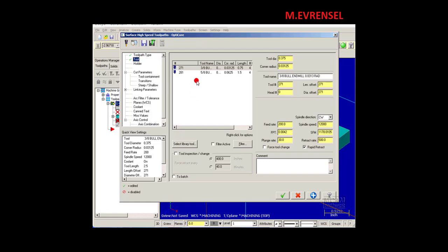The general strategy for using them is use a smaller diameter tool than you might traditionally, but use a very fast and light feed rate. So with the traditional toolpath, I might use a 3/4 or a 5/8 end mill. But with this part, I'm going to select a 3/8 end mill. My feed rate is going to be pretty quick at 200 inches a minute.